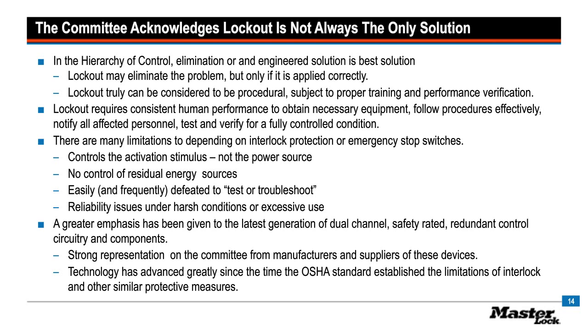It dumps air pressure. It turns off hydraulic pumps and creates automatic draining of hydraulic pressure within the system. All these are excellent engineered solutions that can be considered when the risk assessment has been performed and the dependability of these control factors are taken into consideration.